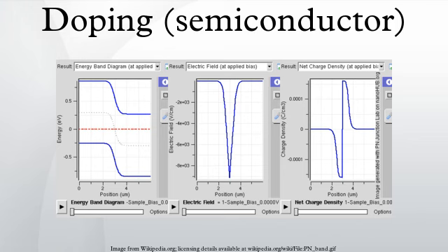Although compensation can be used to increase or decrease the number of donors or acceptors, the electron and hole mobility is always decreased by compensation because mobility is affected by the sum of the donor and acceptor ions. Doping in organic conductors. Conductive polymers can be doped by adding chemical reactants to oxidize, or sometimes reduce, the system so that electrons are pushed into the conducting orbitals within the already potentially conducting system.